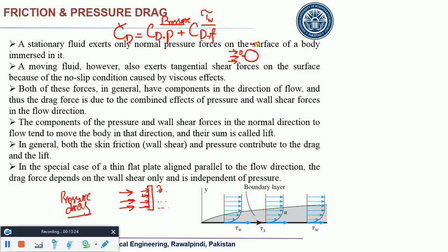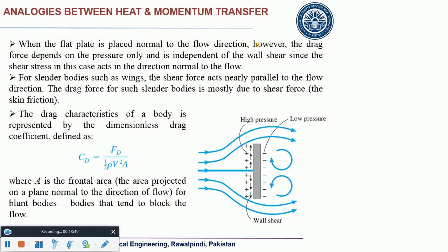In case of turbulent flows, that friction coefficient would increase, right? And why would that friction coefficient increase? Just remember a small V component due to the production of those small eddies which we have talked about earlier. Okay, so these are few salient points which I wanted to share.